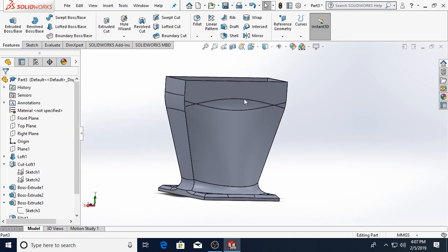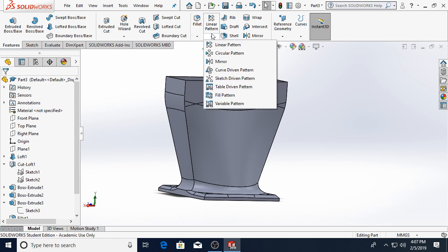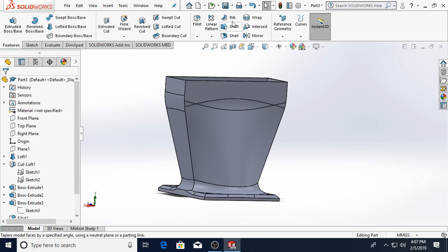Okay, I will also point out that within this field, you have the ability to create patterns, which we're going to talk about next. You have the ability to create some cool features here. You can automatically add ribbing to an intersecting flange for support if you wanted to. You could add draft, which is kind of like a loft, which allows for overshooting material a little bit. You can add shells, which create a three-dimensional object from a two-dimensional profile. It's much like that thin feature mode of the revolved extrusion did when we were creating that bizarre glass over here 2 weeks ago. The one that might be the most useful to you is the wrap.